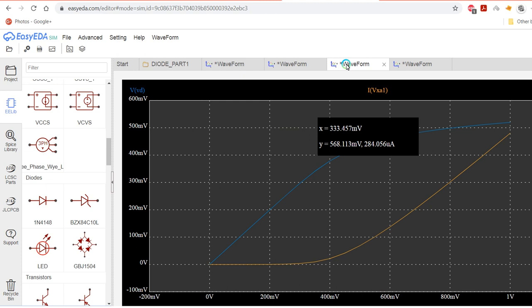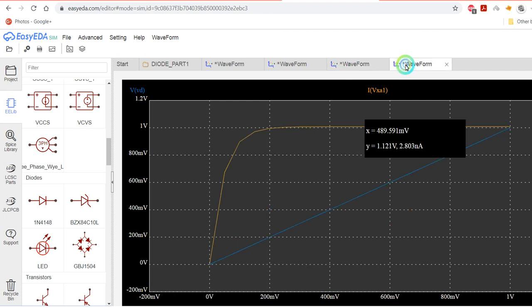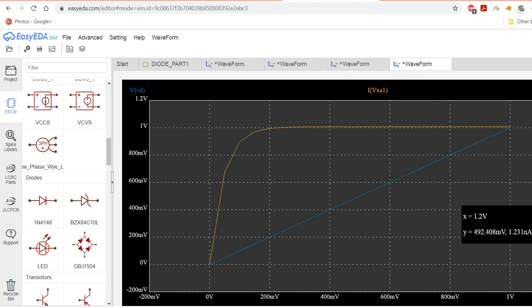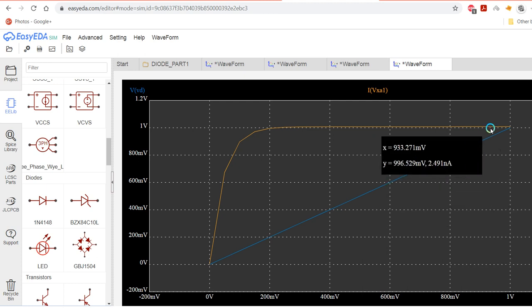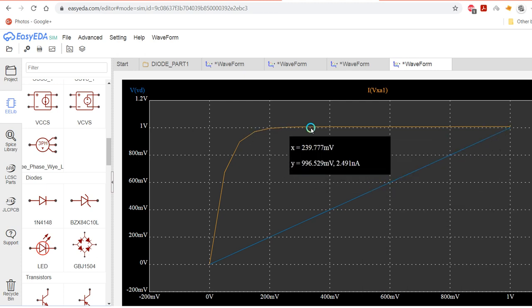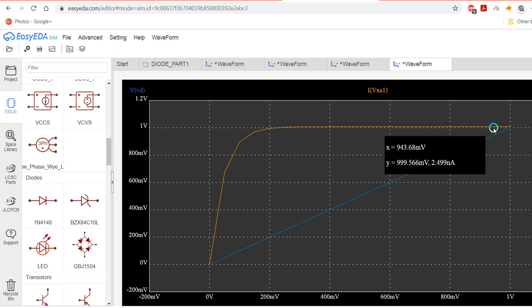to microamps, you can say. Now it's still 50 microamps, 200 microamps. Now you'll see it's a nanoampere unit. So nanoampere is 10 to the power of -9, so that means it's a very, very small current as compared to the current which we have obtained under the forward biased conditions. So here this current, that is 2.5 nanoamperes, which is your constant current, is the reverse saturation current. Now if you further increase the voltage, maybe the diode will break down.